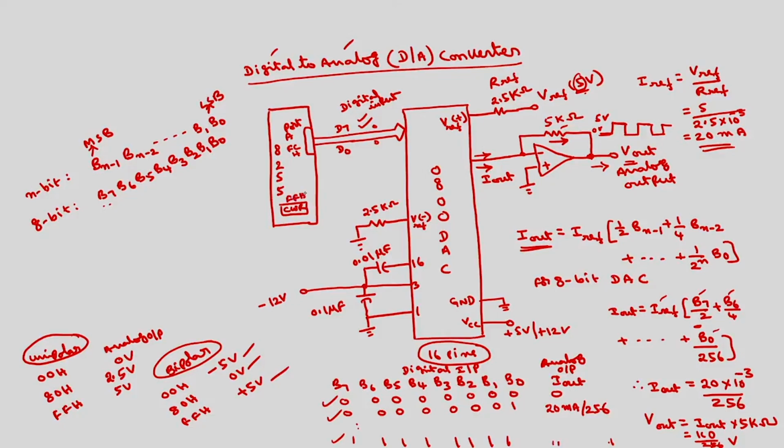So to generate the square wave, first you have to program port A as output port. Move AL comma 80H. 80H will program all the ports as output ports in mode 0, which we discussed in earlier lectures also. Then you have to out onto the controller register whose address is FFH.